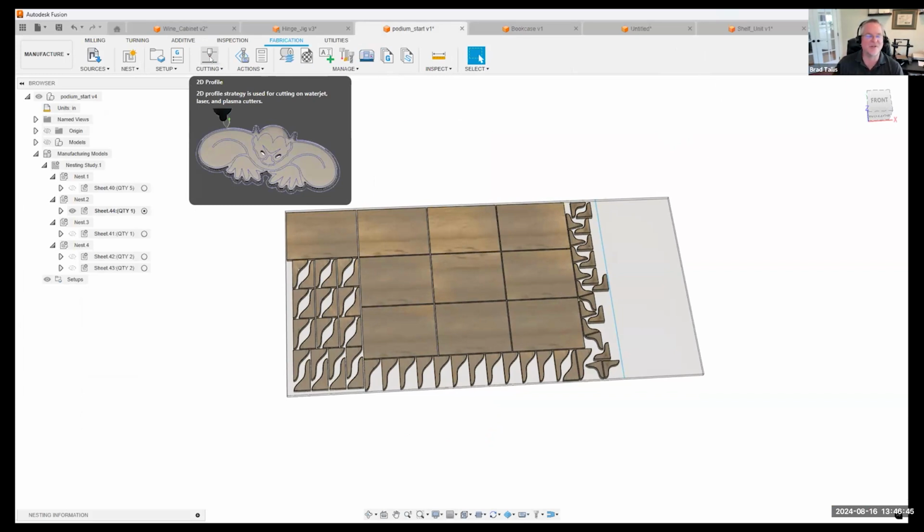And so, yes, there are a bunch of different posts out there. I use Mach 3 personally on my CNC machine, but there are also posts for ShopBot and stuff like that. You would just say, I have a ShopBot, and it gives you options like where's your 0, 0, is it using radius curves, and so on. So yes, there are multiple posts out there, and like I said, if this is something interesting to you, reach out to me and we can do a quick demo to answer those questions.